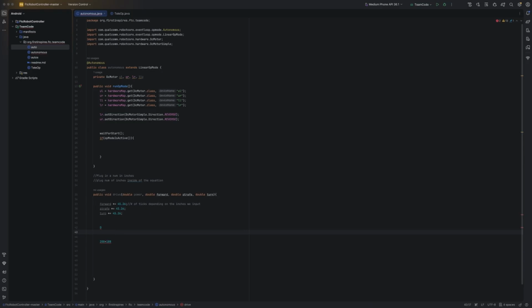Now we have to move 900, right? Let's say I didn't reset. Now I want you to move 200. Now what's going to happen is the motor is at 900, and we want it to be at position 200. So it's going to move backwards, negative 700 ticks, to reach 200. You see what the problem is here?